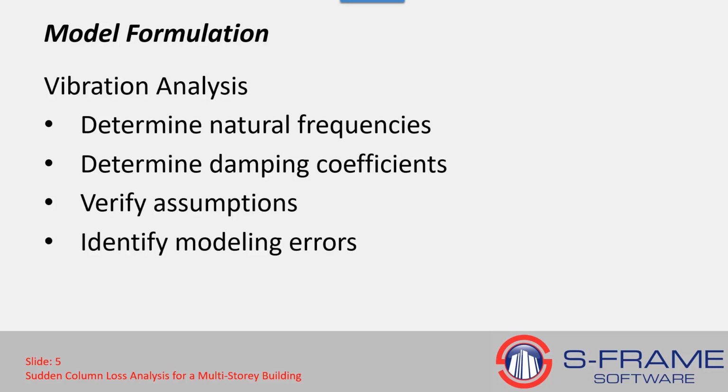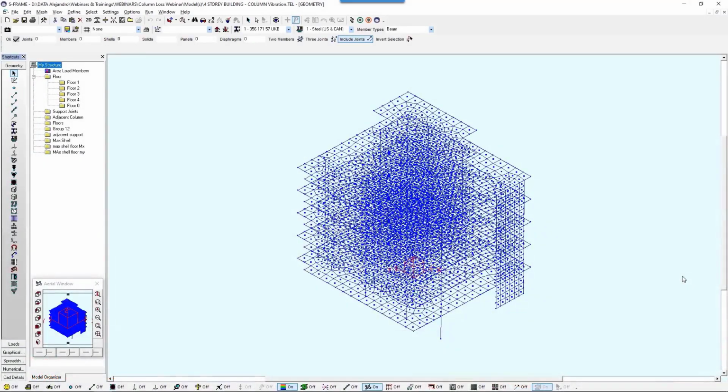Another nice feature of the vibration analysis is that it doesn't depend on any loading. We can actually run it earlier in the modeling process before applying our loads, and this will help us identify any modeling errors before we put a lot of work and time into our project or structure. Let's jump to the demo part of the presentation.